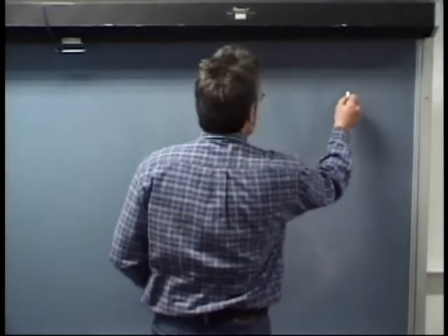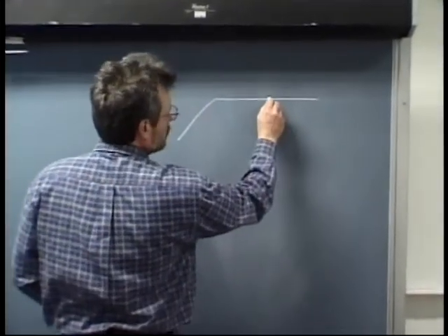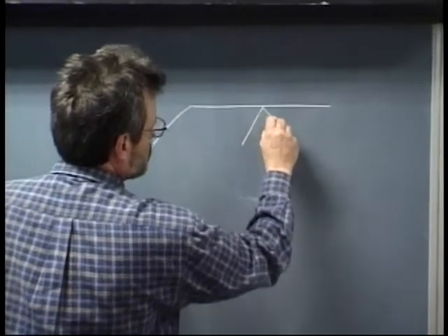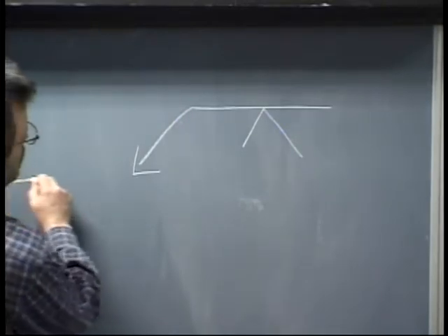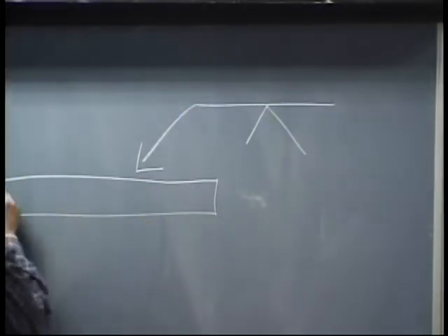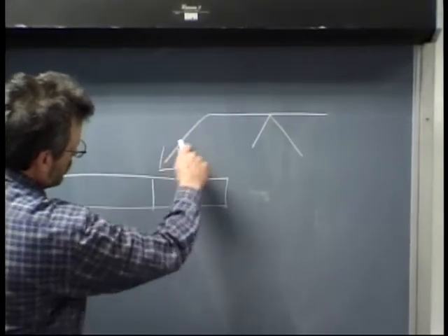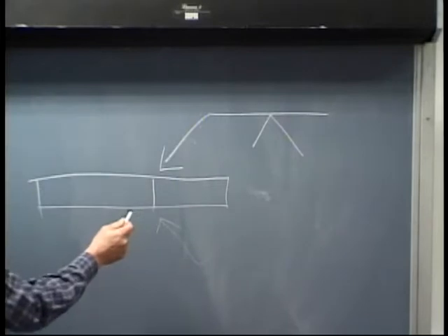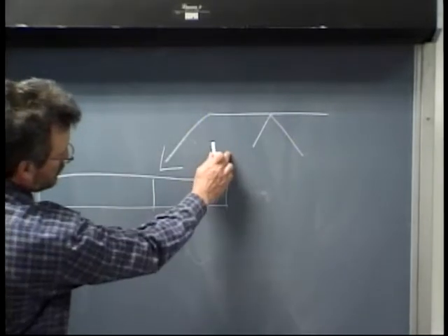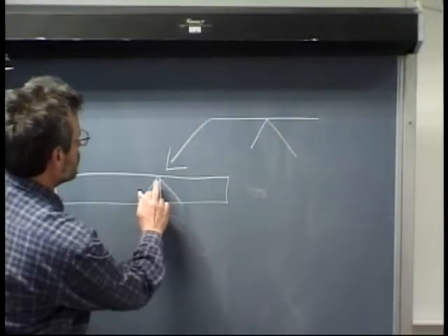So here's our reference line again. Here's our arrow again. And this time we'll have a groove weld symbol. If we have a piece of material like this, we could have it pointing like that. Arrow side means that the work would actually be done over here. And since it's a single V, we would know that both members would need to be prepared.